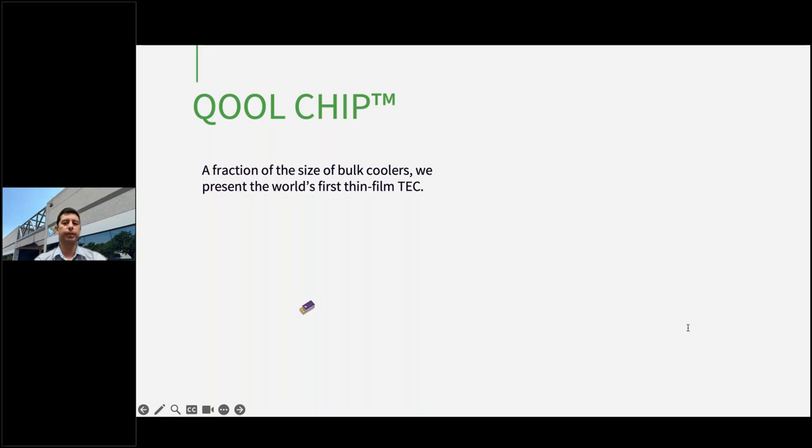Compared to bulk materials, thin film geometries are in the micron scale, whereas bulk materials are normally in the millimeter scale. Thin films are generally deposited onto wafers using wafer scale semiconductor manufacturing, with processes like PVD. Thin films are deposited onto wafers, compared to bulk devices that are pick and place into ceramics.